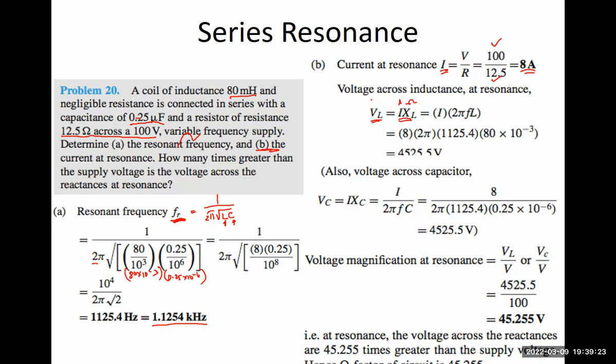And measured in ohms and this is V. So by Ohm's law, okay, so the voltage we could determine by the product of the current and the resistance R. So here, since we are talking about AC, it would be the inductive reactance multiplied by the current to determine now the voltage across the inductor.